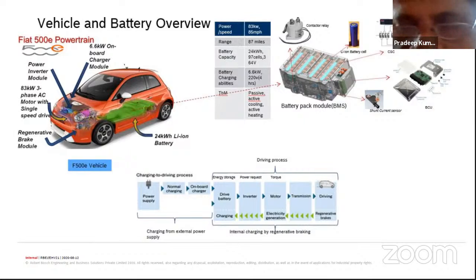If you don't need a sudden brake, but in case of real accident conditions, when you apply a sudden brake, then the entire braking force will come from friction, because there the intention is safety and not to retrieve the energy. But if you are braking in a slow process, that means you are applying braking in a very slow manner, so that you have some braking distance depending on that condition.